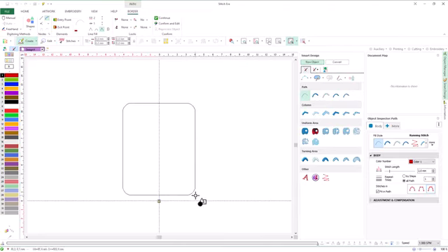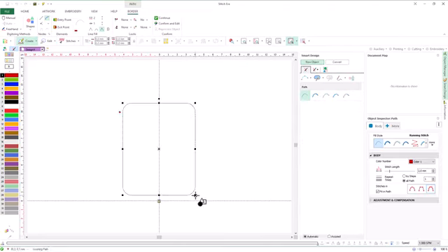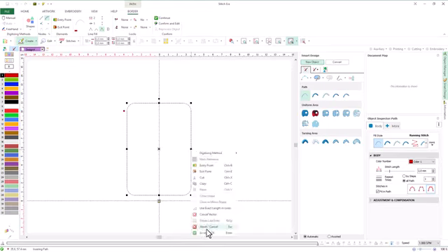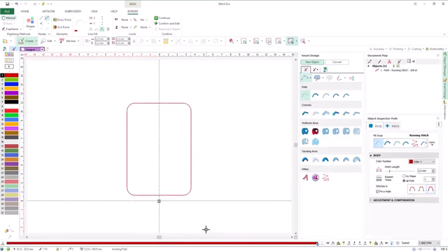Most shapes allow us to move, adjust the size and rotate the shape before we confirm and create the object. Dragging this handle, while holding the Shift key pressed, allows us to change the horizontal size, keeping the center of the shape in its place. Then, we open the context menu and confirm. We may also press Enter instead. The system creates a closed path object with a contour that follows the selected geometric shape.